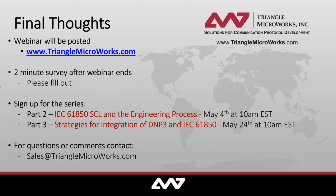There are communication services that we didn't enter in all the details, but we have a classification of data attributes with function constraints, like function constraints for status attributes and for configuration attributes. One way to access more than one data attribute is that I can select all the attributes of function constraint ST, as an example, status information from a data object position. I can also, from an addressing perspective, select even multiple data points, multiple data objects, by addressing the logical node.